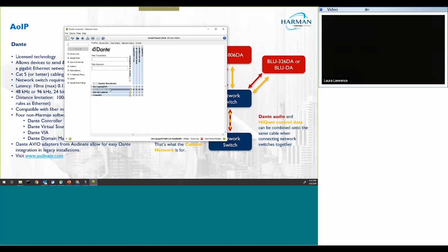Next up, I have an AMX DVX Forte, and of course the new Forte DVXs all support Dante, and they support 8 channels in, 8 channels out of Dante. So if I expand this, you'll see here that the way they do it is they group it in left-right pairs, and I have 4 pairs of left-right audio, which is a total of 8 channels. So I have receive 0 left and right, all the way up to receive 3 left and right.